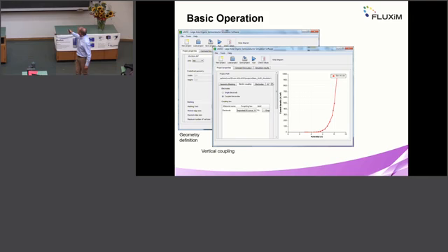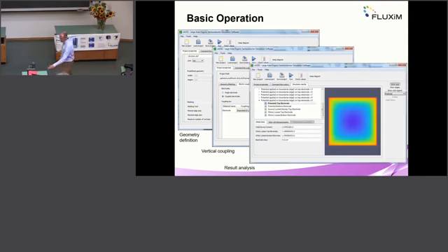And then the second tab, after geometry and meshing, is electric coupling. That's the dialog where you can enter, for each subdomain, so you have electrodes, you have transparent area, inactive area, so for each subdomain in the 2D electrode, you need to specify the JV coupling law. And finally, you just press this play button, that's the run button, which will calculate the solution, and we get the result here. So that's a very quick 3-step workflow.